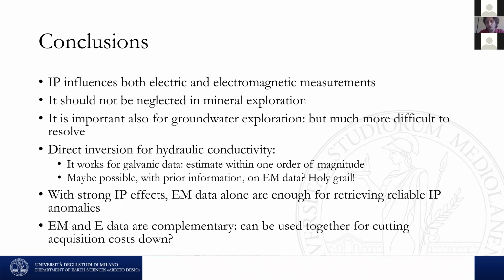Of course, if you lower your base frequency for the EM acquisition, you start to acquire later and later gates. And the longer you acquire, the stronger you will see the IP effect, because if these polarization currents go to zero slower, then they will always give an effect at later times compared to the layers where they do not happen.